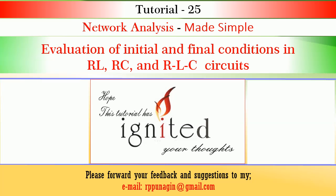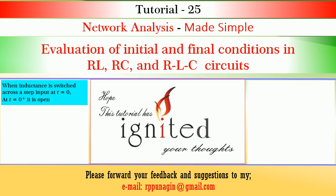Friends, evaluation of initial and final conditions of any given network is very easy and interesting if you are comfortable in basic concepts and little of mathematical knowledge. You also have to acquire the skills of identifying the changes in the connectivity of network elements after you draw the equivalent circuits. Regarding the behavior of inductance and capacitance, I suggest you remember and recall only one statement, that is, when inductance is switched across a step input at t is equal to 0, at t is equal to 0 plus, inductance is open.